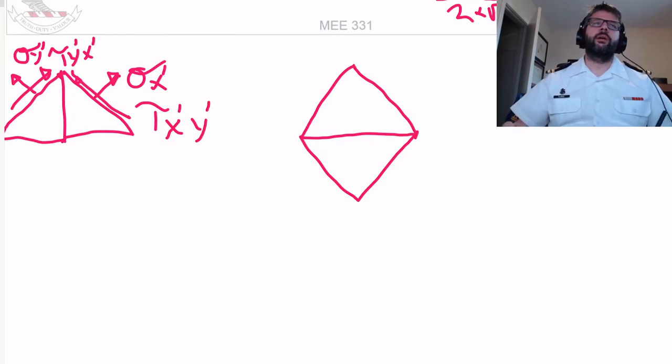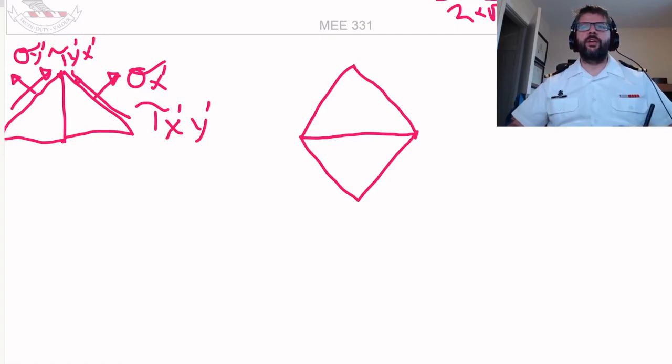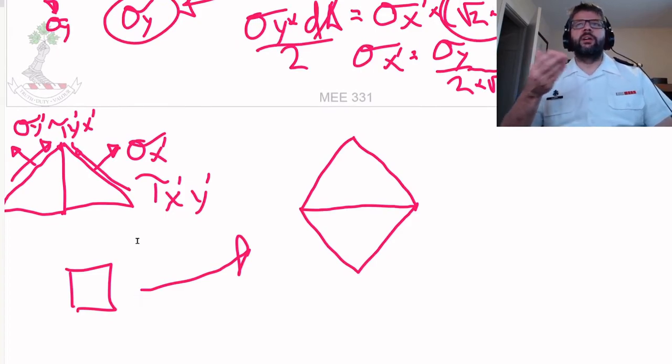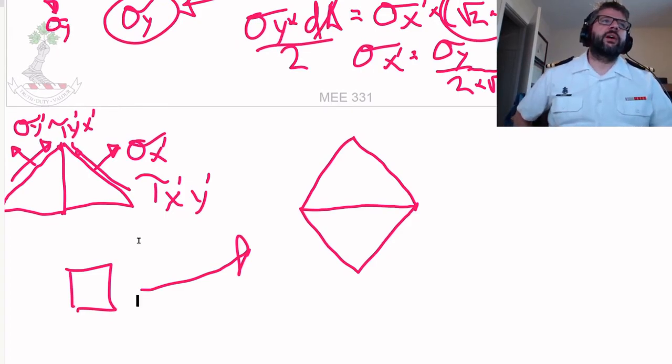So essentially, we could use the same process to transform from this to our new rotated shape in terms of the stress levels. So we rotated, and this shows us how we're looking at the stress determines how we calculate it. So the angle of orientation of our coordinate system very much matters when we're calculating that.